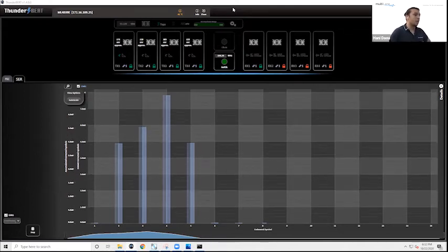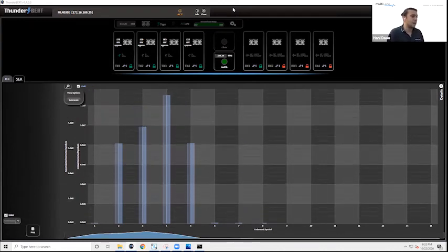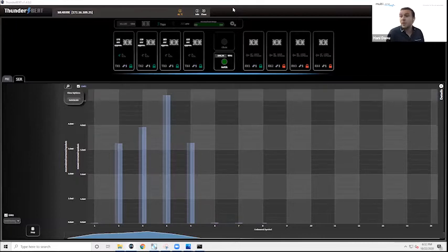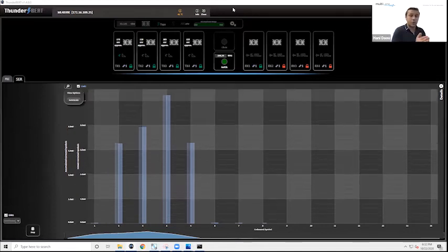So let's see. How do we know the FEC margin in the GUI? The FEC margin that we are offering you is really the same sort of visibility you'll get in a real life network switch. We're giving you the SER, and the SER is really the indicator of FEC margin, because it's telling you, okay, I am not showing any code words with 15 symbol errors or 14 or 13.